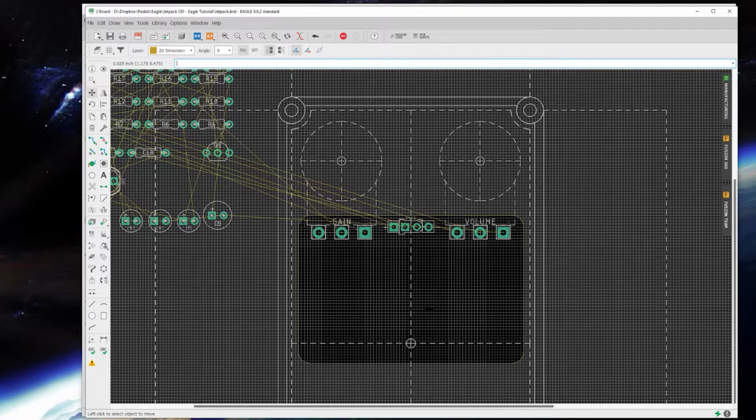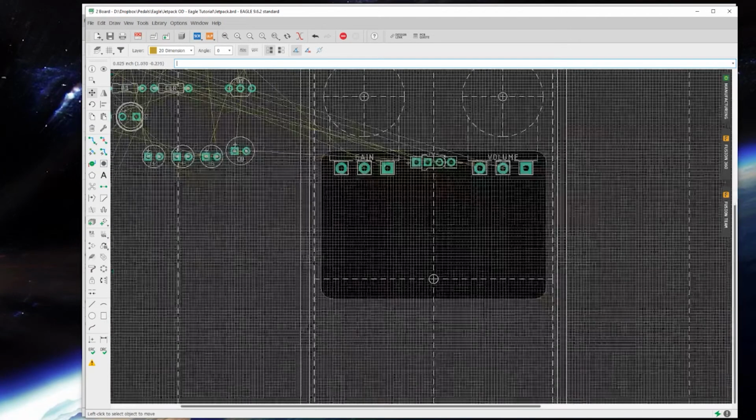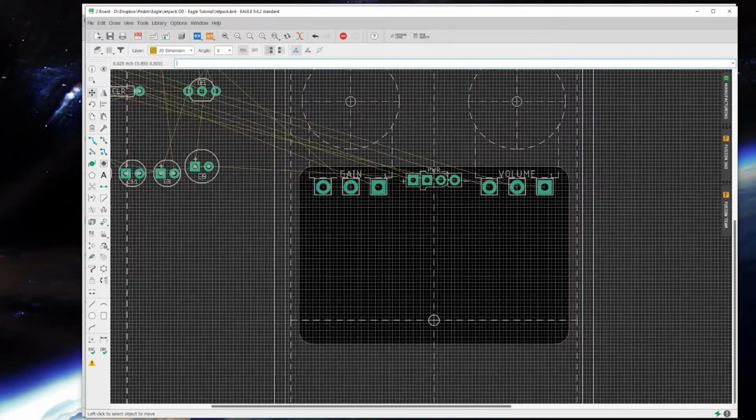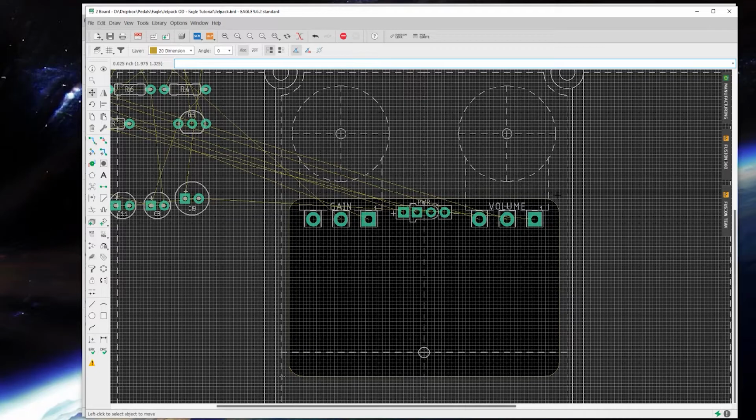For this tutorial, we're going to be focusing on a dual layer board, and the one that will be for fabrication from a fab house like OSH Park or Elecrow or JLC. So the way I approach this step, I like to have ground planes, and that's even reflected in my etchable layouts on the blog.